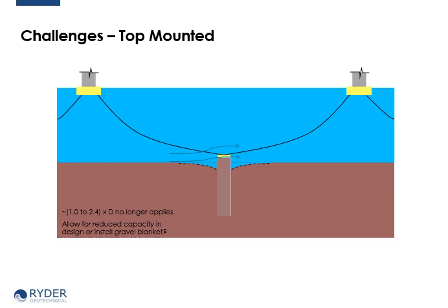However, because there is not an infinitely long foundation in the water column, the 1 to 2.4 times D no longer applies, and the scour extent may be greatly reduced, and potentially the requirement for installing gravel blankets is also reduced. And since the vertical extent of the scour may be reduced, there may be an option to reduce capacity as opposed to installing gravel blankets.